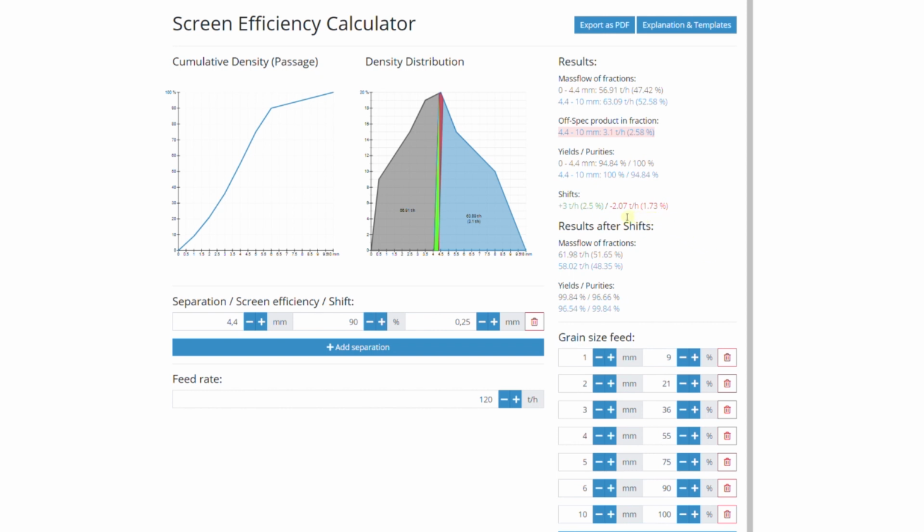The red value indicates the additional screen value obtained that, however, does not correspond to the desired grain size, but due to the adjustment of the delta, also ends up in the finest fraction and thereby contaminates the end product. So by shifting the separation, we also accept a simultaneous reduction in purity, which decreases in the first fraction while it increases in the coarser fraction.